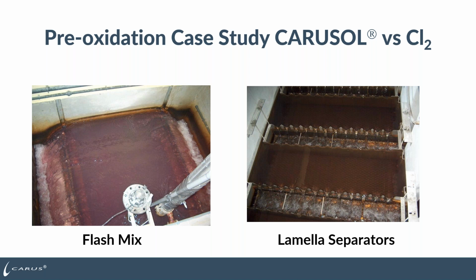And you can see that distinctive pink coloration of permanganate as it splits in the flash mix and goes to the two separate 2.5 active flow processes. So in this case, the flash mix permanganate's being added along with their coagulant. And then they add micro sand. They go through a rapid mix area where that sand, the polymer and everything reacts, and the solids stick to the sand. They take away the agitation, the sand drops out carrying the solids with it.